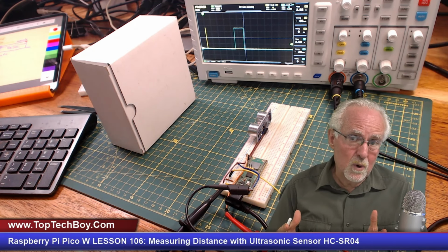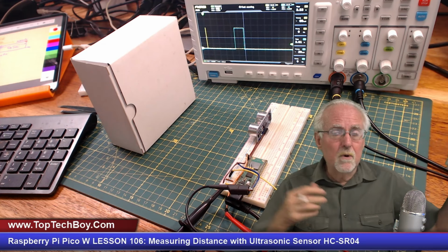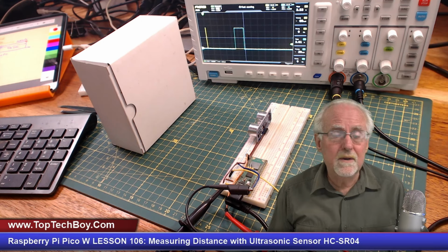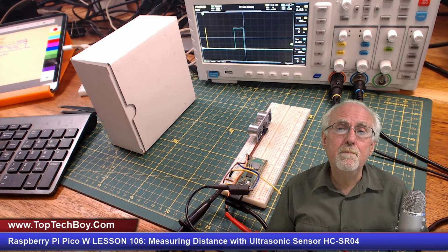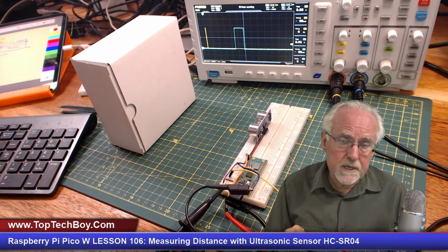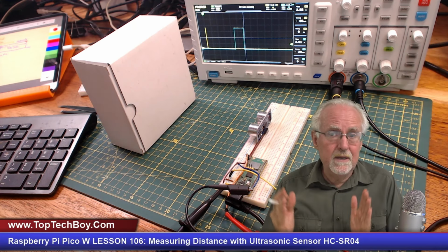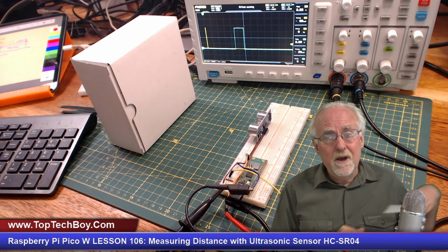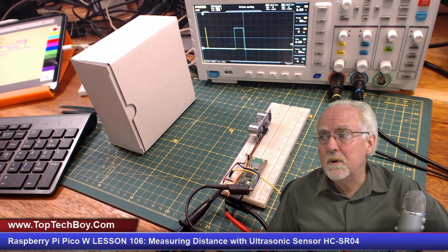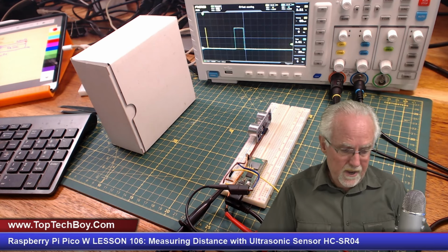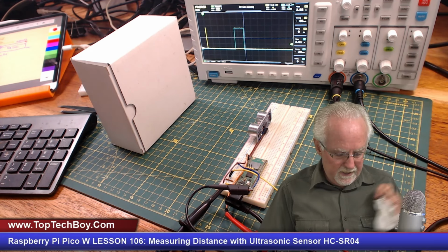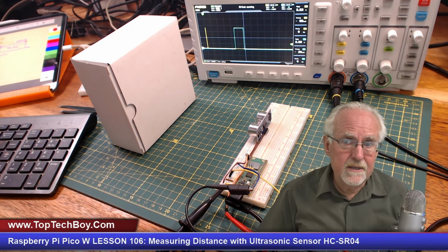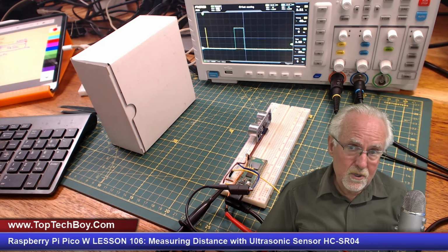As our code becomes more complicated, all of a sudden MicroPython, while it's supposed to be timing our pulse perfectly, goes out and does random strange things, and you can never depend on the trigger pulse that you're generating, and you can never depend on the timing of how you are timing the duration of that up pulse. And so we would be setting ourselves up for disaster if we were using this in a real application, because we never know exactly what MicroPython is going to do related to